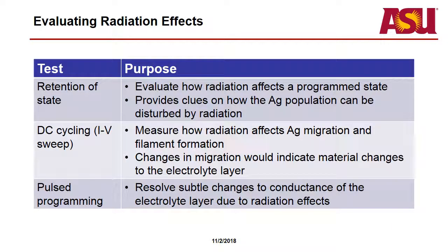Now that I've explained three different ways of testing these devices electrically, I'm going to go over how that corresponds to what we might like to capture during radiation tests. So for retention of state, while in a radiation environment, you want to evaluate how well the device can maintain that state throughout the duration of the radiation exposure. For example, if you're in a low resistance state, you want to see if radiation in some way drives that resistance state lower or higher, breaks the filament essentially, or if you're in a high resistance state, how susceptible the device is to suddenly becoming programmed.